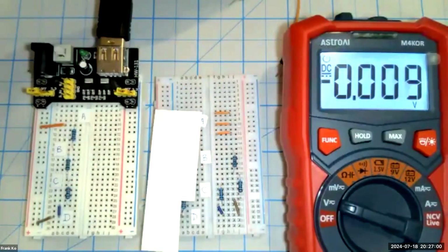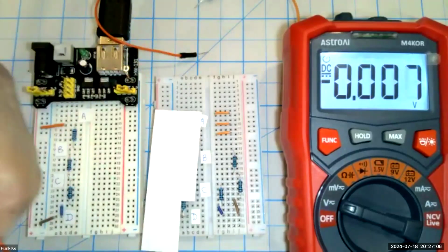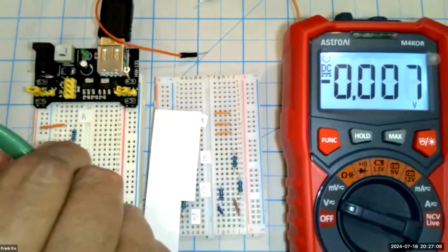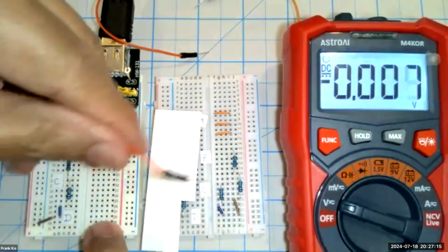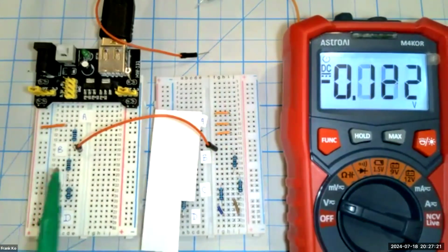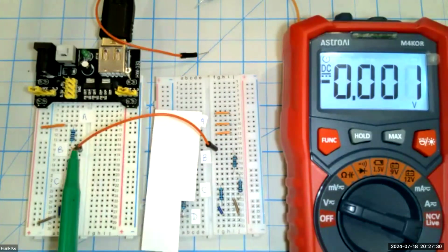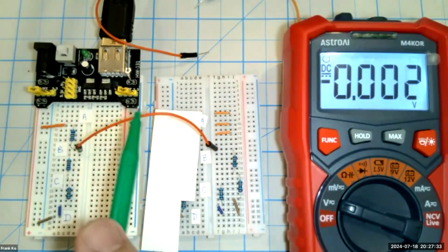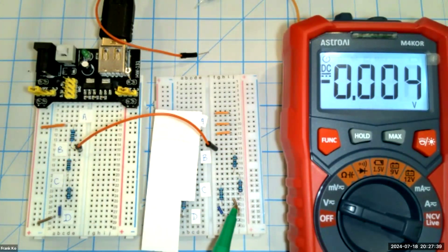So I'm going to use these jumper wires because I'm going between boards. I'm going to insert point B. So here is point B over here, and I'm going to attach it to point B where I need it on this side, right there. If you look at this carefully, point B is the point between R1 and R2. I have 4 volts here originally without any wires attached to it. We measured 4 volts here. We hope to see 4 volts over here, but you'll find that we won't be able to because these load resistors change the balance of the circuit.